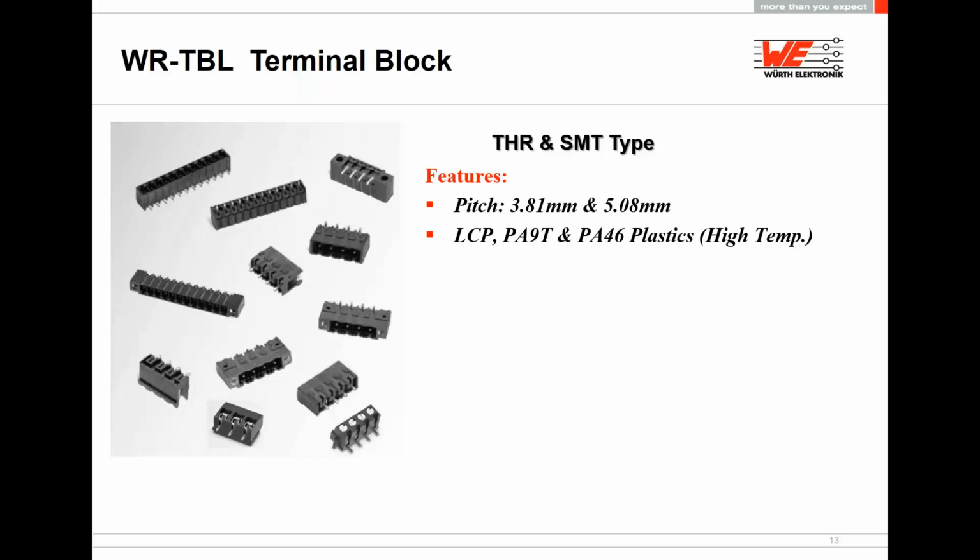LCP and PA90 and all of that high temp plastic material. As I said, it's black. When you see it's thermoblock black from our end, that means it handles a through hole reflow.